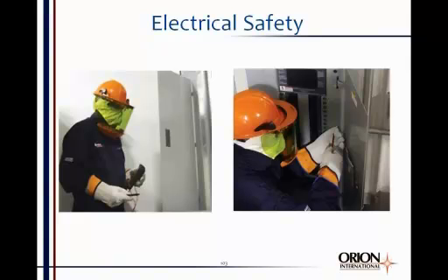Again, this guy has on the arc-rated clothing. He has voltage-rated gloves, has on leather over protectors, and he's using a good quality voltmeter. He's ready to go to work on energized electrical equipment.